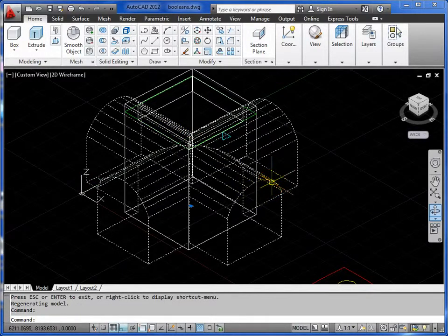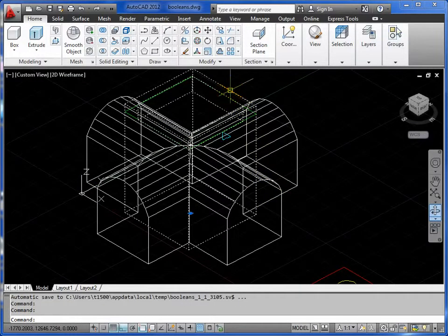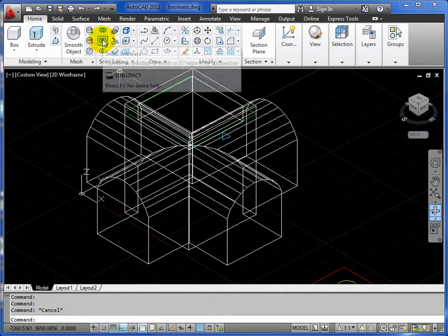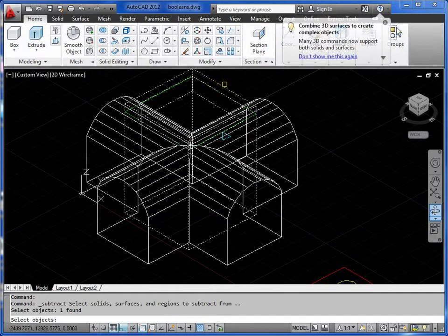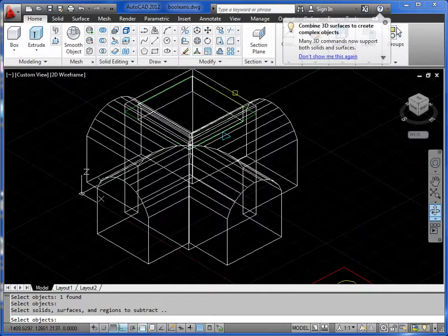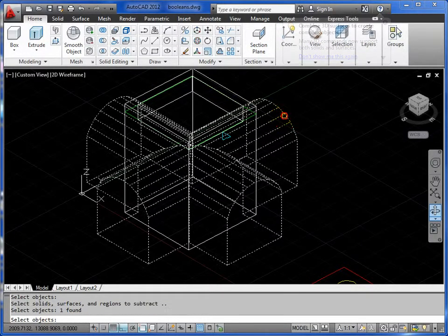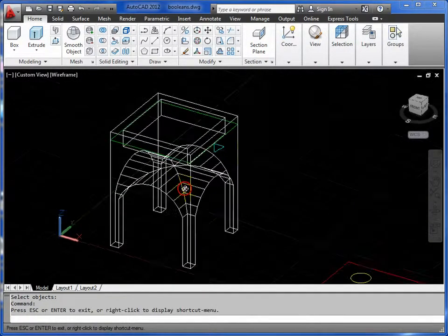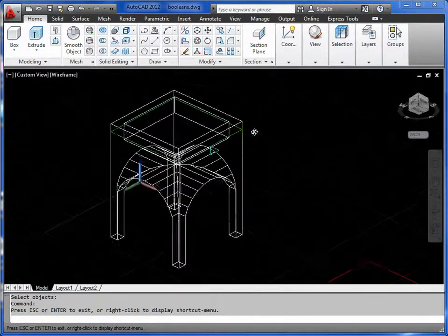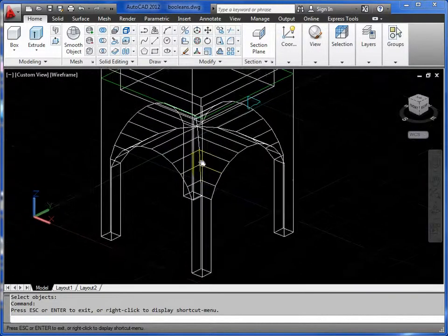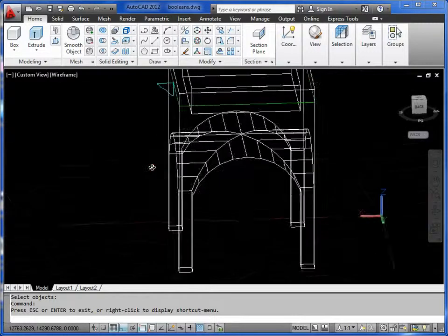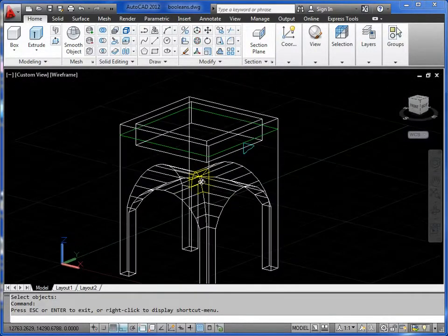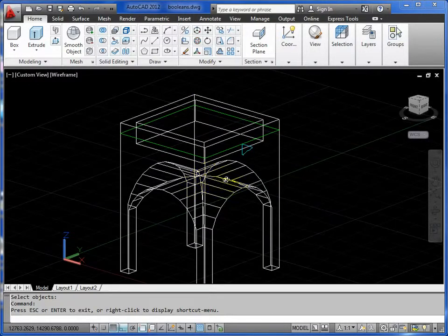And now we can take this cross shape from the main lump to give us our vaulted roof. So subtract from the big shape, return, then pick your subtracting shape and return again. Now, instantly people can see the power and simplicity and all the advantages that kind of modelling is going to give them. It's a great little set of commands.